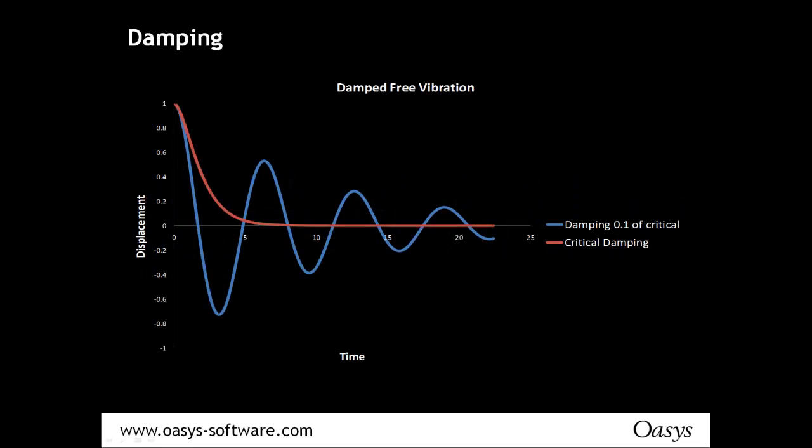Now, if this resonance was unchecked, the vibrations would eventually destroy the structure, a bit like Tacoma Narrows. But thankfully, as I mentioned earlier, structures do have imperfections built into them. These can be accidental, generic imperfections such as steelwork connections, concrete cracking, and so on, or they can be physical dampers built into the structure, deliberately there to absorb the vibration, a bit like you have on your car.